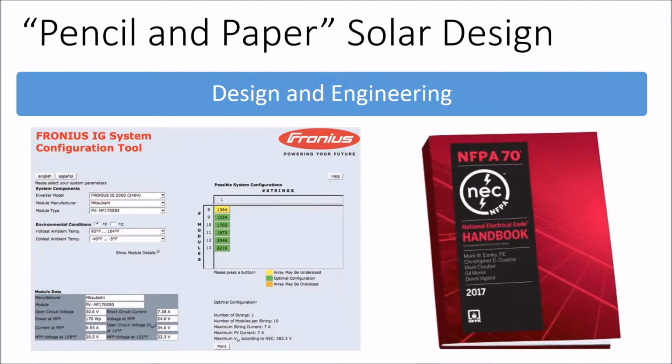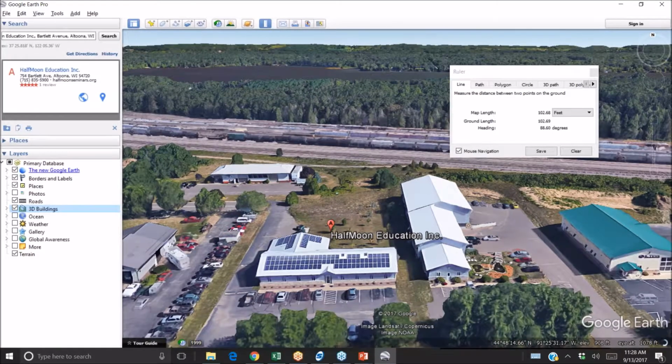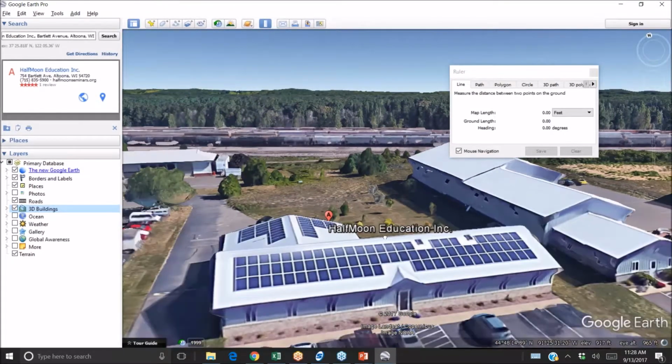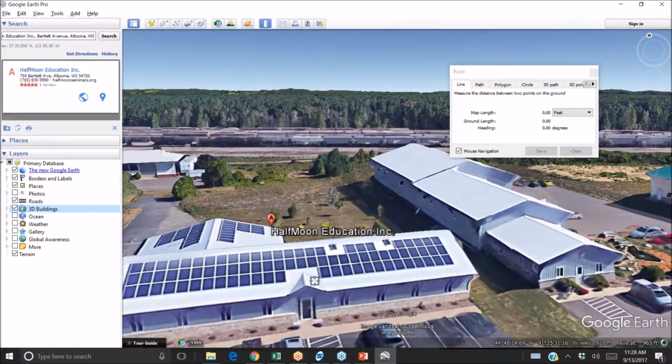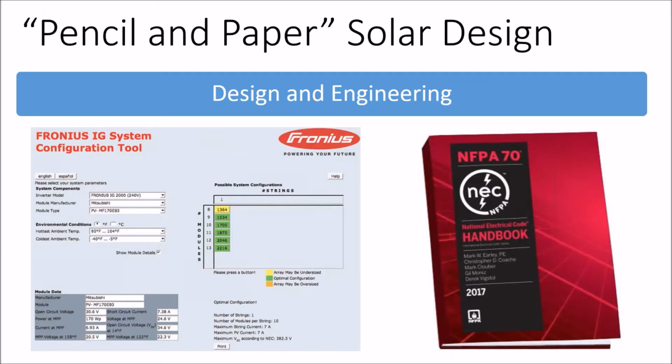The next point, once you've sketched out the roof: solar design is literally how many rectangles you can fit into your usable roof surface. Once you have that roof surface defined, you're just tiling as many panels as you can into it, making sure you're leaving enough distance between roof-mounted objects and that your array is somewhat accessible, especially if you're using things like microinverters. You want your solar array to be accessible at the edges in case you have to do any maintenance work down the road.